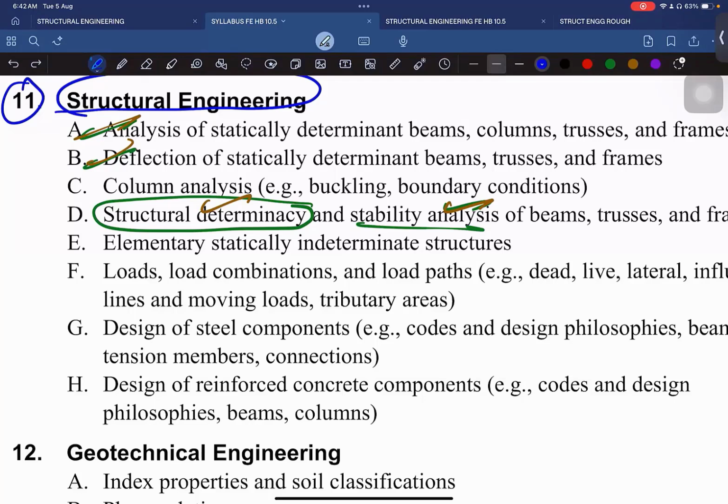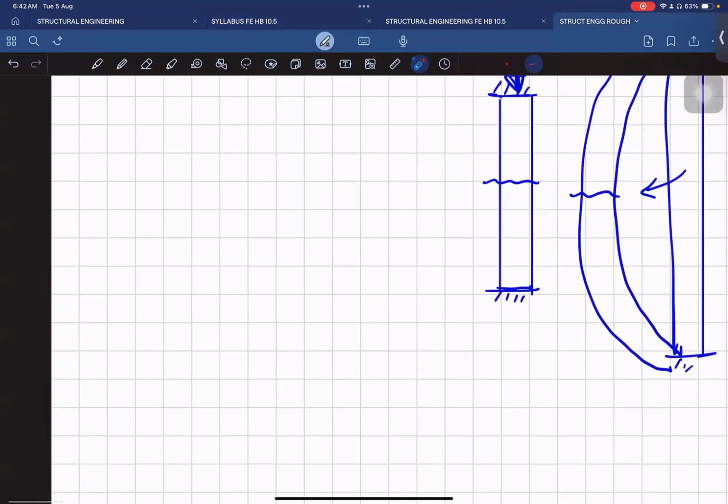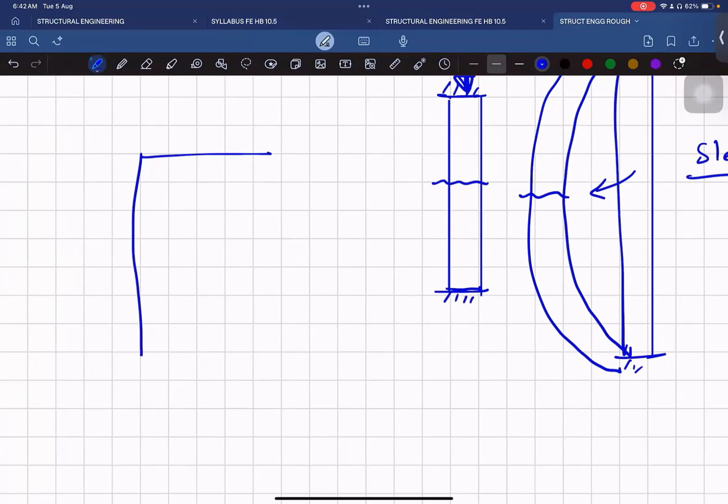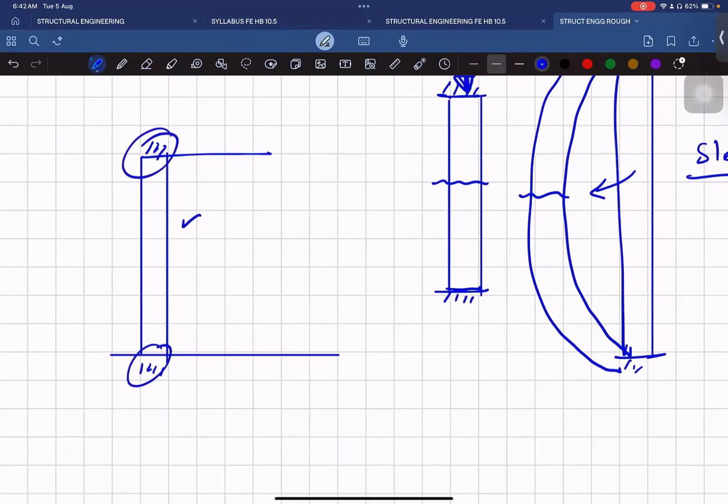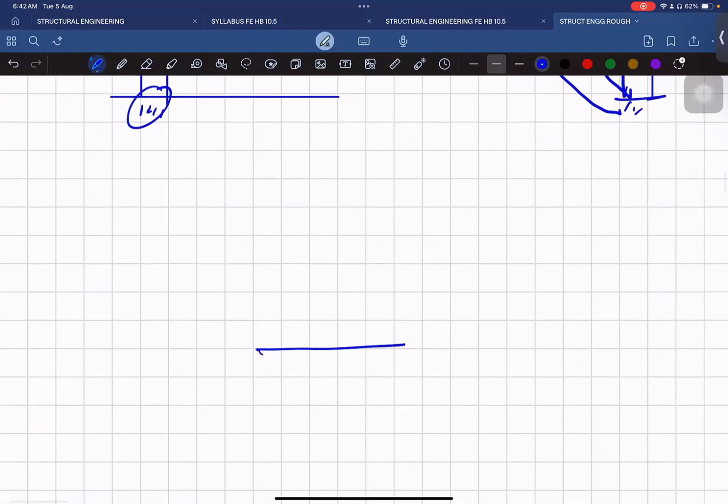And this is clear. And what are the boundary conditions of a column? It's like the top and bottom of the column will be fixed, either rigidly fixed or free in the air. In day-to-day buildings, the columns will be fixed at top and bottom. They will act like fixed edges. This is one kind of fixity of a column, one kind of boundary condition. There can also be columns, like in nature, fixed at the bottom and free to the air. Can you give one practical example?